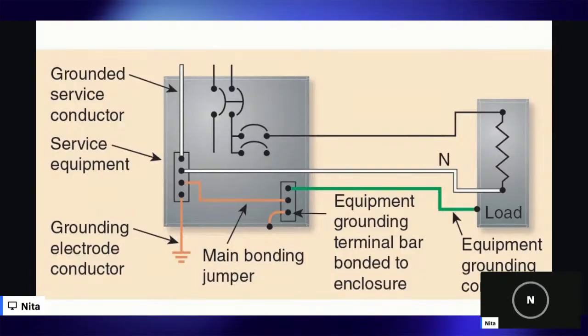But your point about those two-prong outlets is that they're typically older and they do not have a connection to the ground. And you're right, it is costly because you have to open up everything to be able to connect the ground, the EGC, back to the main panel. Most investors would not want to do that, so they bootleg the ground. Again, I'll explain that next week. And that's why we use those electrical testers, to tell if there is a connection to ground. So you are understanding it correctly, Edith, from that perspective.